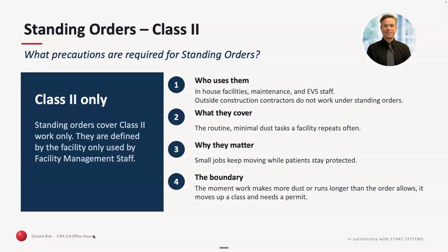Class 2, just as a reminder, if you are a contractor, these don't apply to you. These are only for hospital developed policies. We did not put what those are in the ICRA form. We just said that hospitals have to develop their own orders or work plans or standing orders, as we refer to them. And so I've worked with a number of different hospitals that have done this. They set up a different process for if I'm going to pull cable or rip up tile or rip up rugs or carpet or anything, I have to have these types of containments up. That is only for hospital personnel.